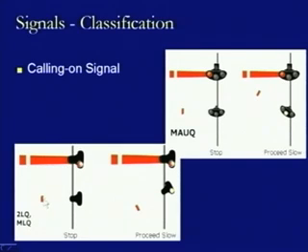This is white with a red band. If it is horizontal, it means we have to stop, but if this is down, it means we can proceed, but because the main signal is horizontal, we have to proceed slowly and cautiously. The same is the condition when we are talking about the upper quadrant signal, which will be working in the upward direction.